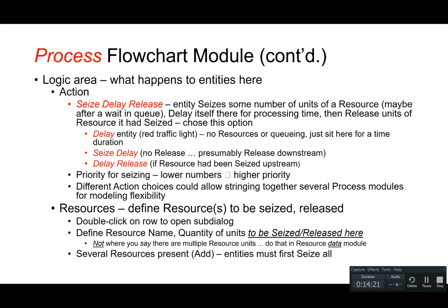The logic area is what happens to the entities here. Under Actions, Seize, Delay, Release: the entity seizes some number of units of a resource. The delay itself is there for the processing time, as we just discussed, and then the resource is released once it has been seized. So choose this option.